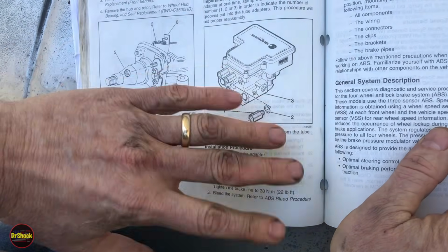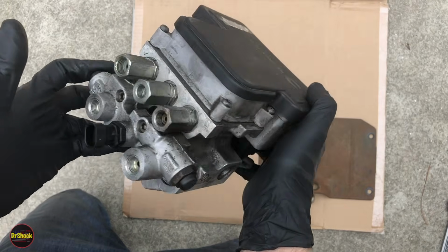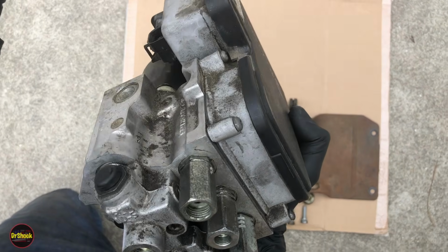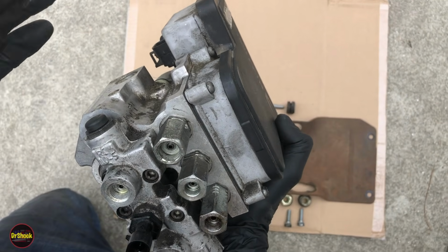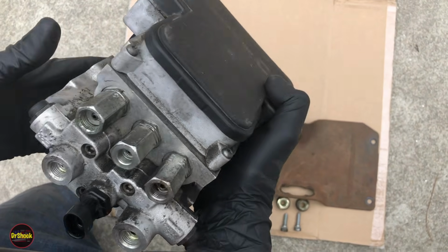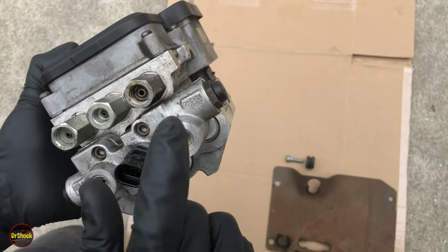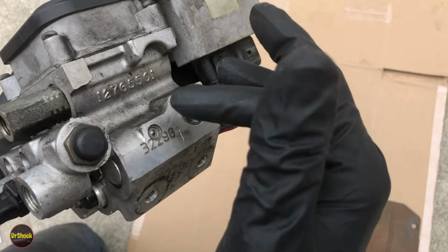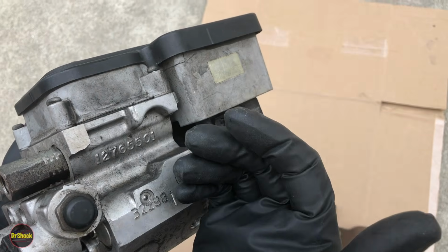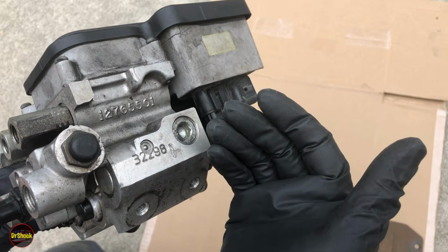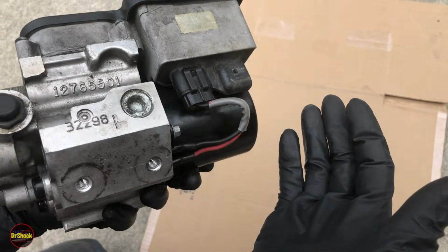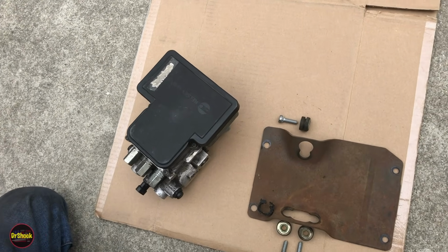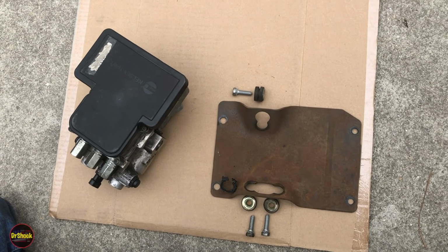We'll do a teardown next so you can see all this stuff. Guys, I'm going to take this apart and basically give you the parts explosion on it, and then we'll talk about the individual pieces and identification across different model trucks. We're going to start with the combination valve and pressure switch, and then we'll work on separating out the tubes, the EBCM from the brake pressure modulator valve, the BPMV. There you go. Say that 6 times fast. So let me go ahead and set this guy over here, get our first tools, and just tear it apart, and then we'll talk about it.